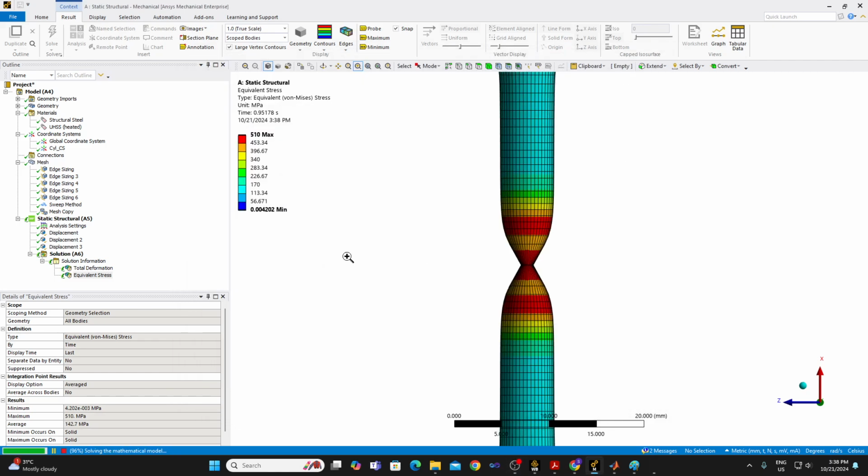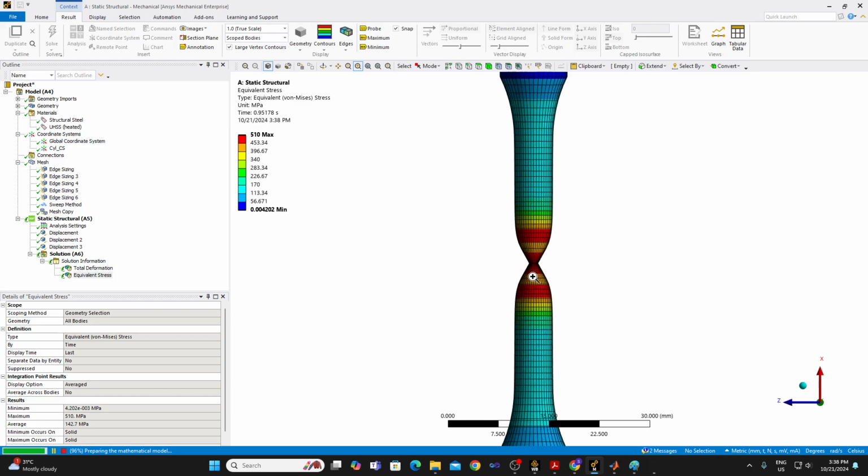So we'll let this simulation complete, and this is only going to progress. Our solution has already converged up to 95%. If you look here carefully, the reason why we took a fine mesh in the middle, now the elements have been greatly stretched. Particularly the elements that are exactly connected to the middle plane are stretched the maximum. We have taken at most 10 millimeters of elongation.